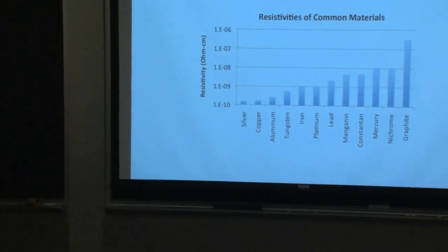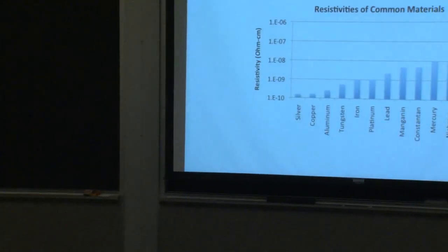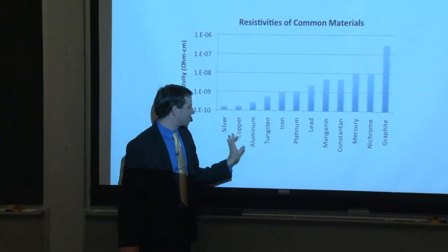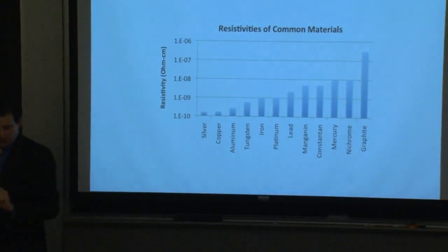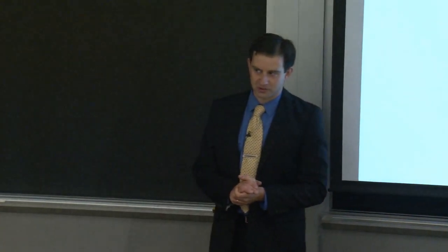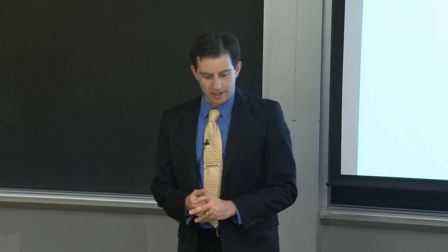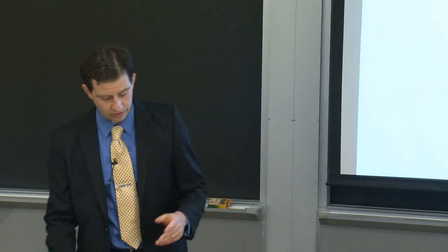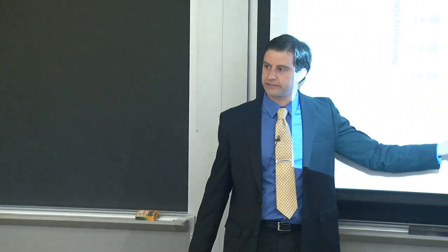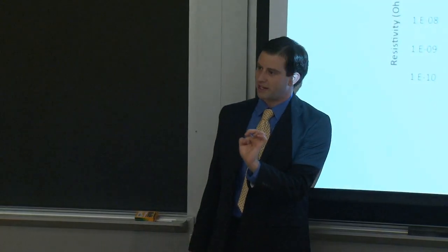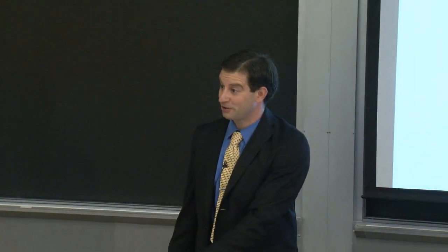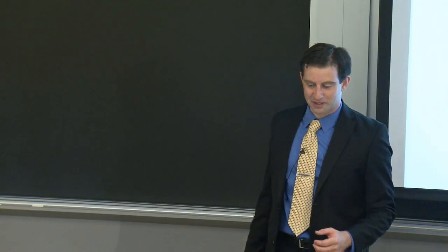Yep, question? Copper doesn't seem that much worse than silver. Is there a better reason? So yes, absolutely. Copper doesn't seem so much worse than silver. The contact metallization pastes to date have mostly been using silver. Copper can oxidize fairly easily. So that's one downside of copper. Another problem with copper is that it's a very fast diffuser. It's very tiny. And so the elastic strain energy term as it tries to move through a lattice is very small. And as a result, it goes deep.